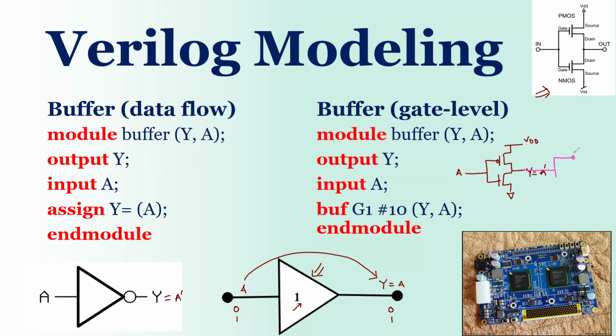So what I'm going to do is add another CMOS inverter right over here. So this is my circuit. This is VDD, and this is ground, and right over here I have used another input. But now the input here is complement of A, and the final output will be the complement of A bar, which will be A. So just have two CMOS inverters in cascade to get Y equal to A. So this is how the buffer circuit will work.